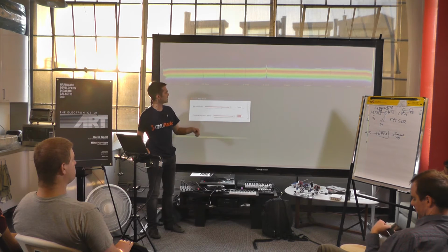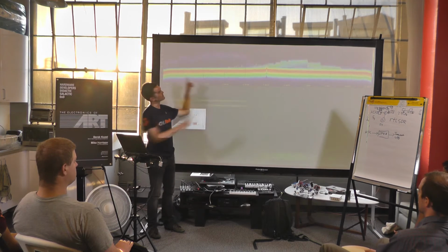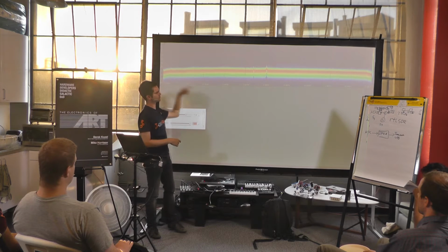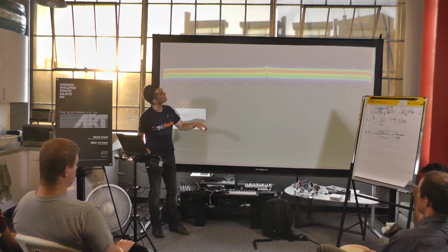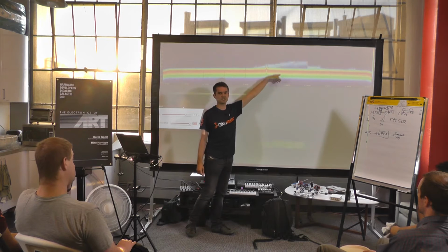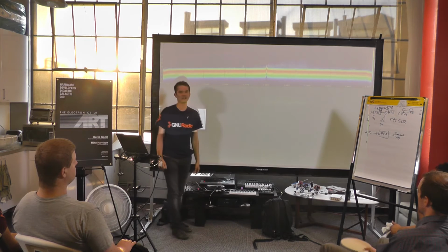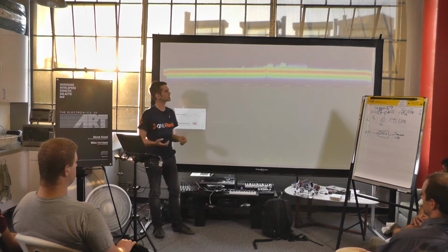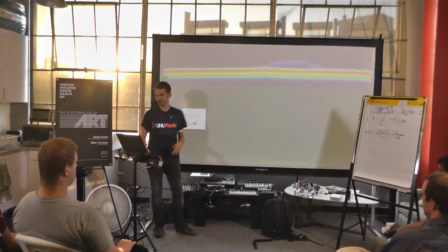And unfortunately, the lights are glaring it out a bit, but you can actually see the packets flying by in the display here. So this is a much wider signal. Right now, we're looking at 50 megahertz worth of spectrum from minus 25 to plus 25 off of the center frequency here. And it's a bit hard to see, but you can actually see that most of the time, it's not transmitting. So this is a histogram of the power. So we're seeing small spikes here that are showing when the Wi-Fi is actually transmitting. If one of us pulled out a phone or something and started firing up YouTube on the Wi-Fi, this would basically just max out. Well, depending on your connection.